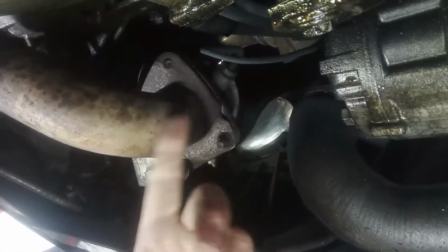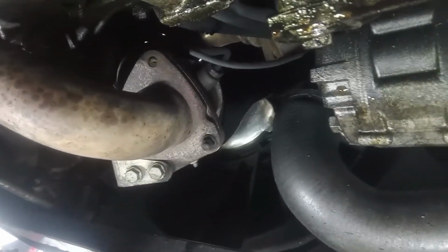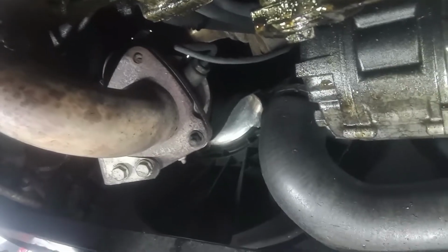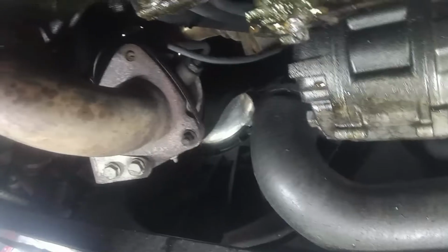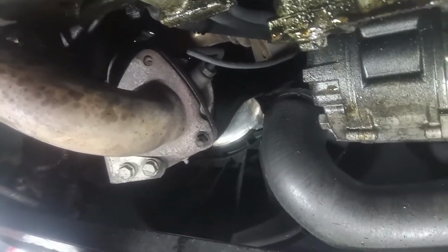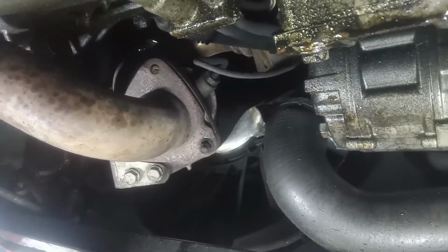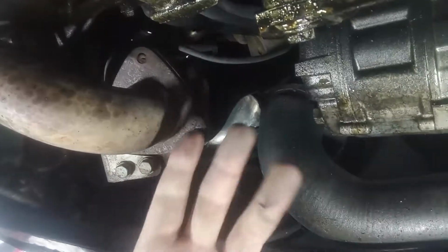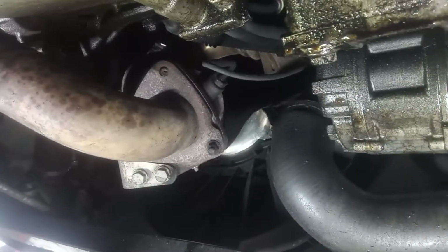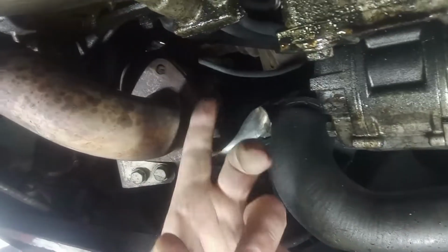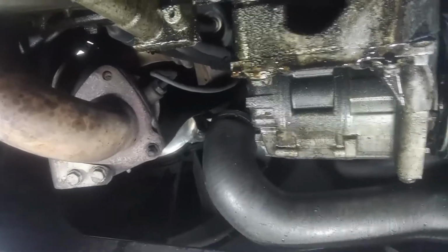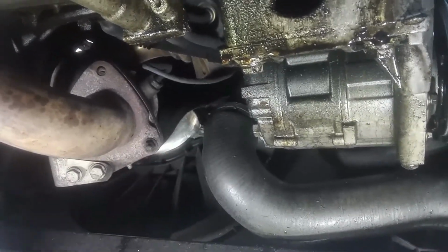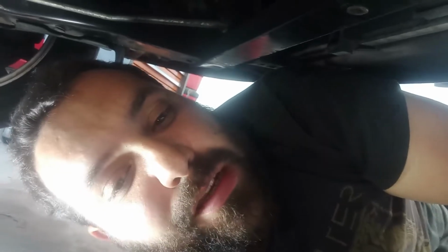So if you have a leak over here, the sensor will never be able to read the correct amount of back pressure of your exhaust. And with that also give you false readings, and the calculation of the regenerations are completely off. So that being said, with or without DPF, you can never have an exhaust leak so close to the engine. This is a fire hazard because the engine is very coated in oil. Very nasty.